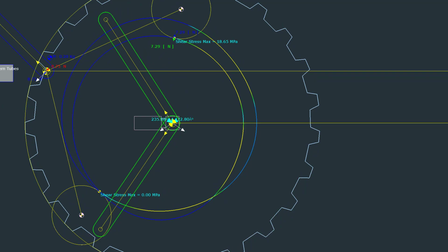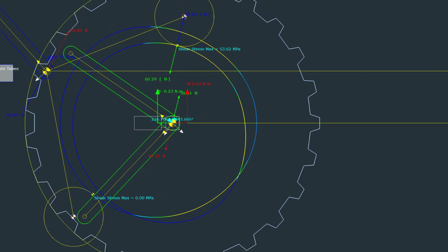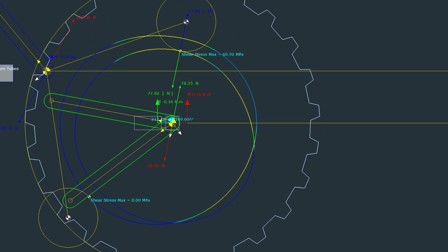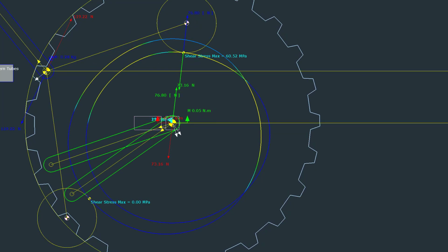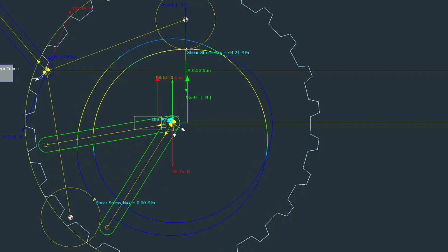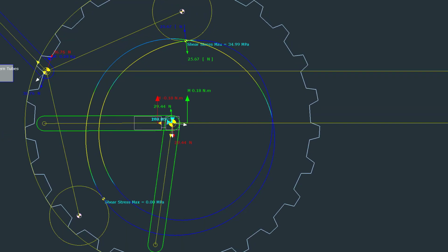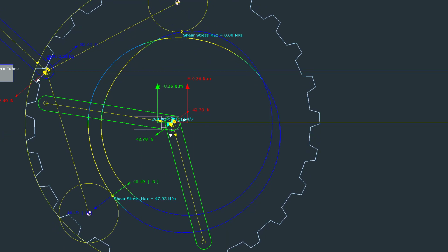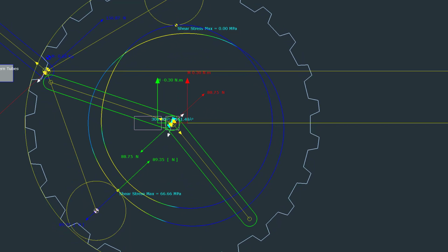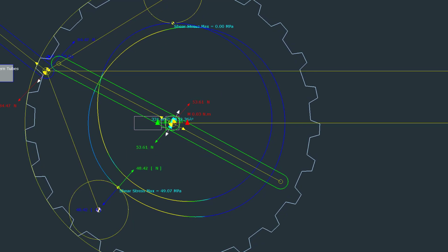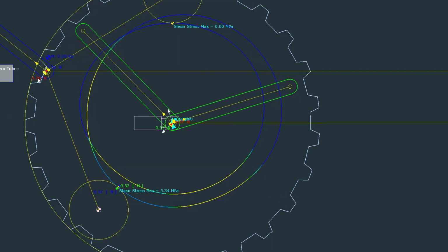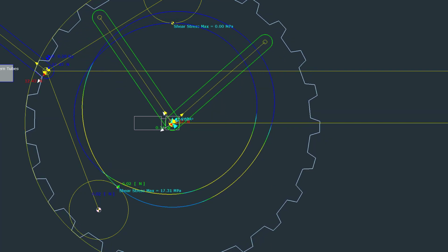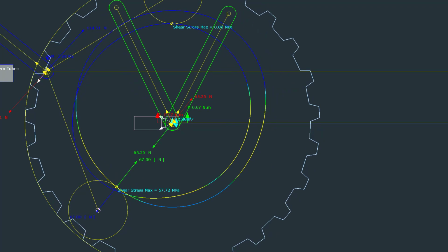The conjugate cam function ensures that load is only ever applied to one of the cams specified in the cam list at any time in the machine cycle to avoid a static indeterminacy. As the load switches direction, one cam will begin to be stressed while the other cam's stress will become zero. In reality, provided a cam has been designed and manufactured correctly, there will occasionally be a relatively small load on the passive cam flank because of the anti-backlash preload usually applied to the rollers.